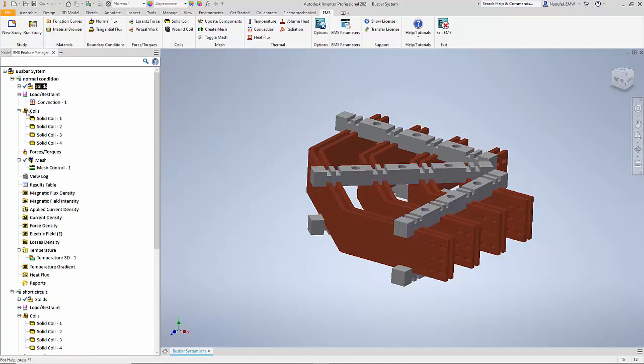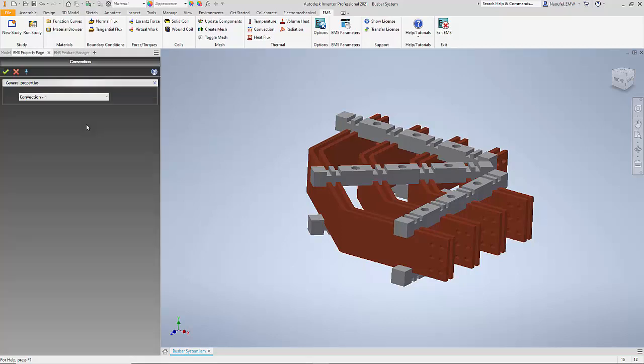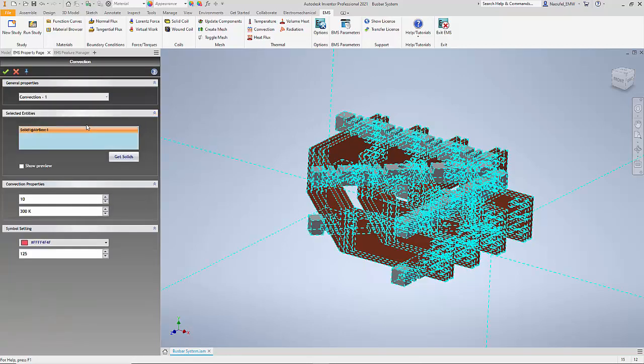Now, during the normal operating condition, there is going to be an I squared R heat loss in each of these bus bars. To evacuate this heat, we apply what is called a convection boundary condition. In this convection boundary condition, all the outside surfaces of the bus bars, as well as these holding bars, are convecting to the surrounding air using natural convection.